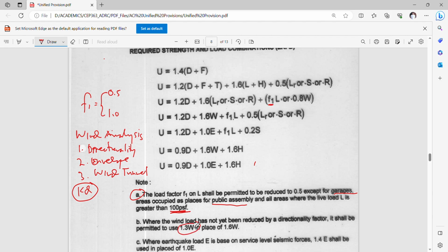in that regard. Okay, so KD is not applicable, but take note that if you already use KD, you have to use 1.6 W to make your calculation perhaps more compliant with the code requirement given to us by the ACI.